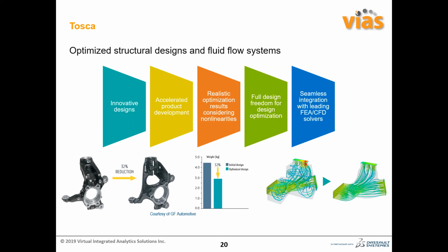But here the idea is that you start your design by choosing a design space, and then you apply your loading and boundary conditions, and you decide a particular kind of optimization criteria, like you want to reduce your mass by achieving a certain amount of stress, or you want to have a certain kind of frequency response by minimizing the mass. All these scenarios are basically an optimization task, and you're having certain constraints on the design.